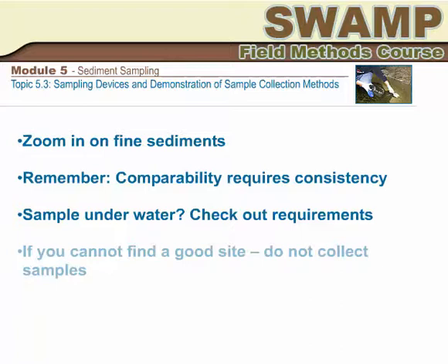If a suitable site for collecting sediments cannot be found at a station, sampling personnel should not collect the sediment sample, and should instead attempt to reschedule the sample collection. If this is not possible, make a note so that the missing sample is accounted for in the reconciliation of monitoring events during preparation of sample collection cruise reports. Sites that are routinely difficult to collect should be considered for relocation or elimination from the sample schedule if appropriate.